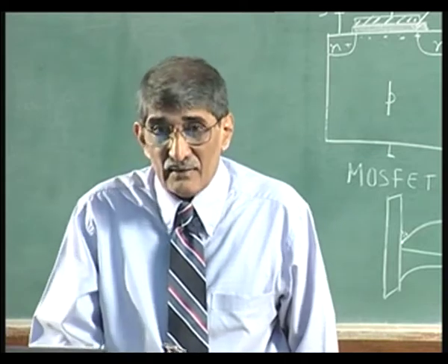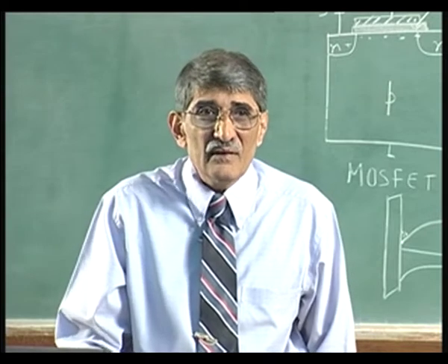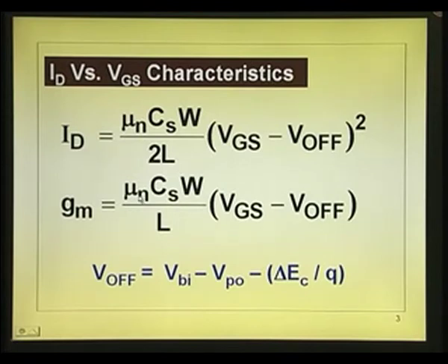Now, we also argued in the previous case of the MESFET that when you go to higher and higher electric fields, the mobility will degrade because of the field. But then you write everything in terms of the velocity, and then you can get the velocity overshoot benefits, which are very large. In this connection, I would also like to mention, suppose I go to very high fields, you get the velocity overshoot effect, and you get the transfer of electrons from the lower valley to the upper valley.